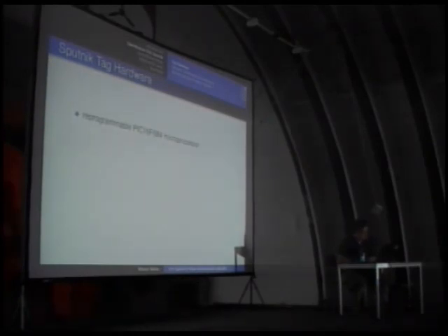Sorry. The hardware consists again of a PIC16F684 microprocessor. We mainly chose this microprocessor because it's A, cheap, B, draws virtually no power, and C, you can buy it pre-programmed, and no other manufacturer, to my knowledge, provides such services. You can buy directly from Microchip, so you don't have to pay annoying fees for distributors that are just reselling the devices. So it's in the end cheaper. But I personally also don't like PIC microcontrollers because they are not really high-level language capable.